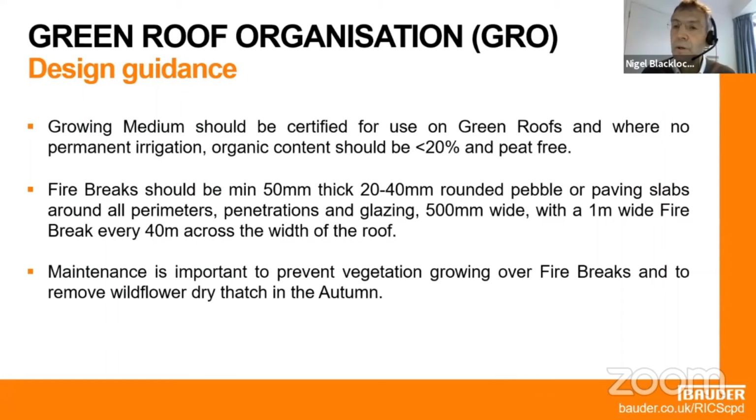A very important point is if you're going for some of the wildflower type green roofs where they have a lot of thatch that is left from after the summer, it's very important that they're properly maintained. Now, any green roof manufacturer would always advocate good maintenance, but unfortunately it's a thing that the client often neglects to do. But there's a double reason for doing it now.